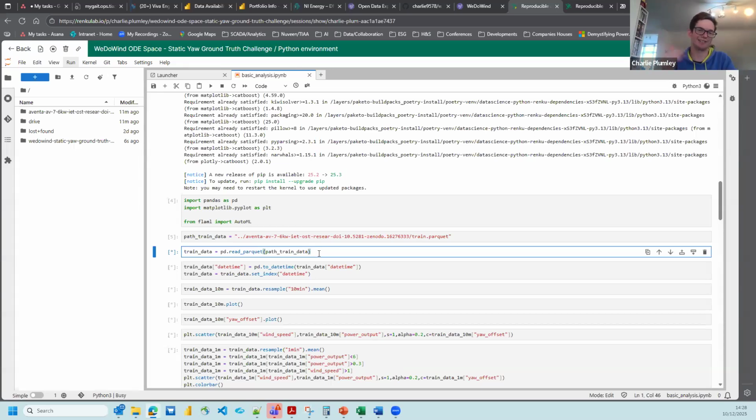So there's a parameter in the turbine control system where you can basically adjust it. What we don't actually know is, when the parameter for the offset is 0, whether that means the turbine is pointing perfectly into the wind, because we haven't installed a LiDAR or another device to check if there was a yaw misalignment to start off with.